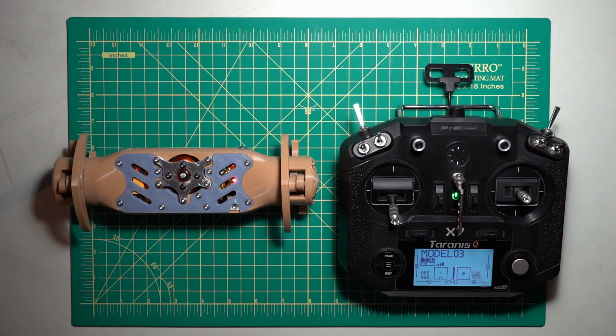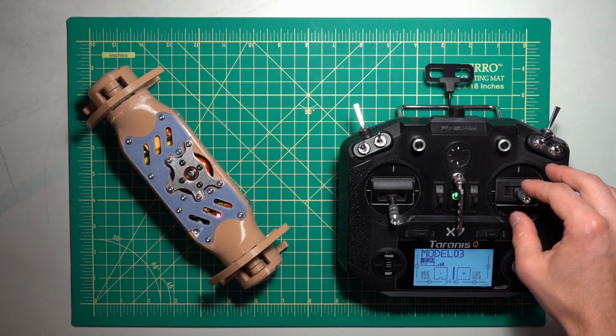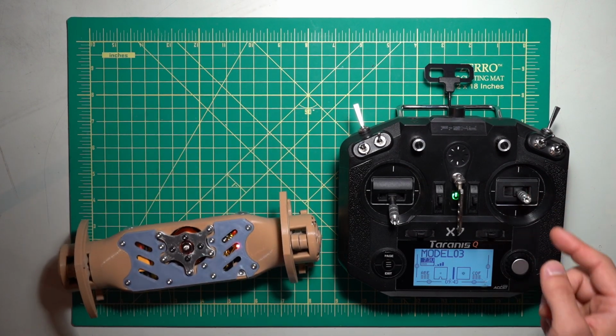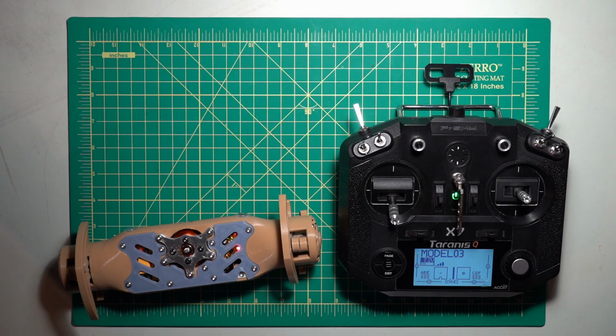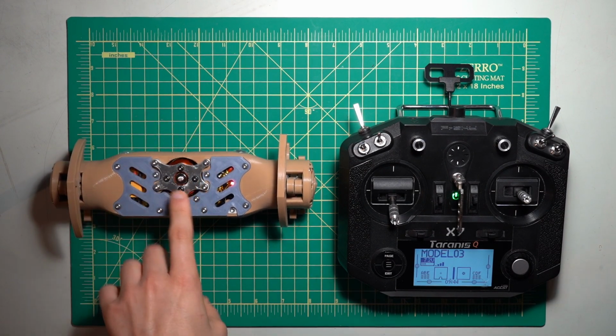Let's diagnose the issues here as an example. When I move the stick forward, the robot spins. When I push it to the side to turn, it goes in a straight line. This is a pretty classic issue of a motor being inverted. If just my steering was inverted, I would still be able to go forward, it would just turn in the wrong direction. To determine which motor is causing the issue, I'll watch the robot carefully.